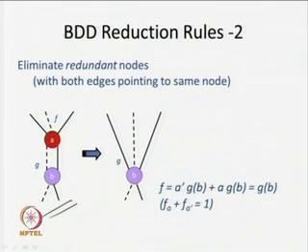When A equals 1, again it points to this non-terminal node. Now you just see that when A is equal to 0, the functional value depends on B. So, when A equals 0, we get A dash into G B, that remaining portion. Similarly, when A equals 1, again we get A dot G B, because we already know A equals 1, and this is the remaining portion that we have to evaluate.